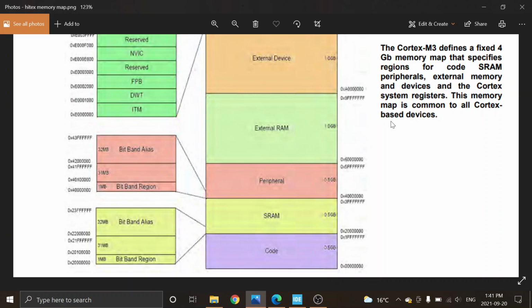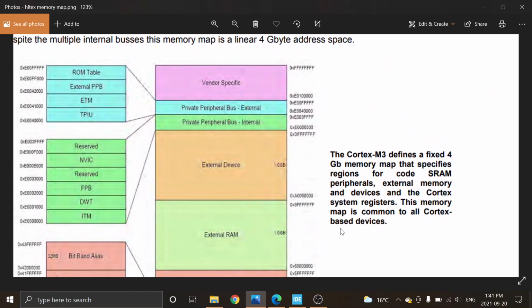You also have the ability then to put in external RAM. In fact, your board will allow you to hook up an external static RAM chip or NAND chip or TFT display, not just interface with SPI.